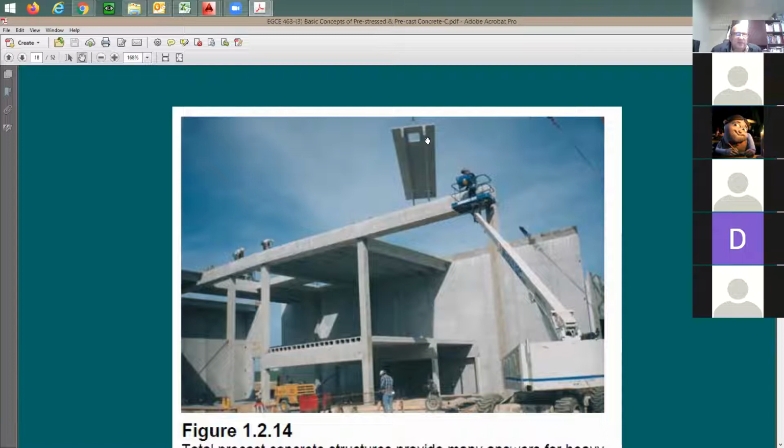So what range are we talking about for the double T? Can I tell you this? Start at 20 inch, 22 inch, 24, 26, 28 inch. This can be the range. So the depth here is let's say about 2 feet. How about this one here? I'm going to say maybe 8 inches. There's some 6 inches, there's 8, there's 10 inches. So this is good for short spans. It's going to be economic. But once you go to a larger span, you really need to have this double T. What spans are we talking about for double T's?